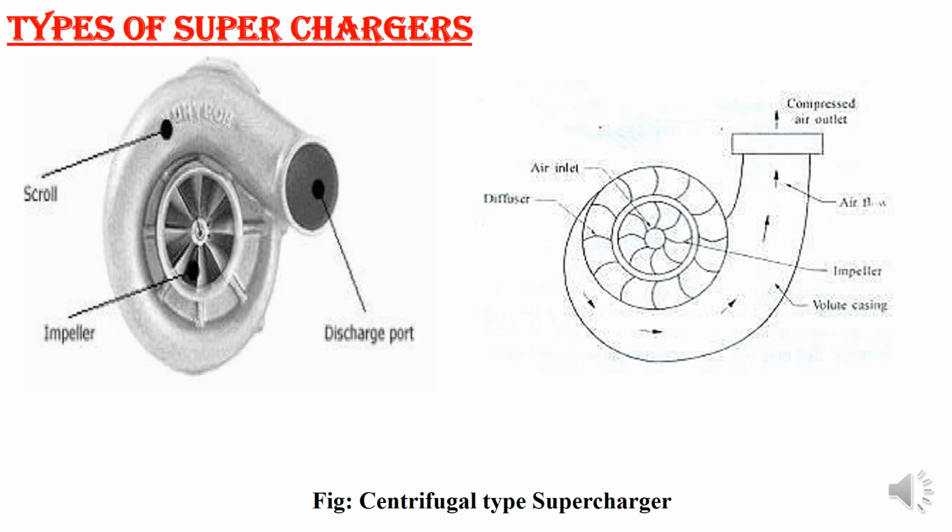So for types of compressor we have the reciprocating type, rotary type, centrifugal type, root blower type, and vane type of compressor. All those things we have already gone through. Here we are mainly concentrating on centrifugal type, rotary type, and vane type. Reciprocating we are not going to use because we sometimes need energy from exhaust gas to run. So reciprocating will lead to some problems because it might be bulky in nature, lower power may not be transferred, a lower pressure ratio cannot be transferred properly, and all those problems will be there in the reciprocating motion.